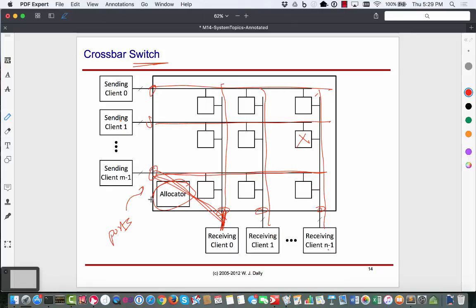This switch-based architecture is very common in networking, whereas bus-based stuff is what used to be the case on chips and boards. But because the performance requirements have been going up and up, in the recent 10 years or so it's very common to have what they call networks on chips. So you see these crossbar switches and all. FPGAs are one great example.